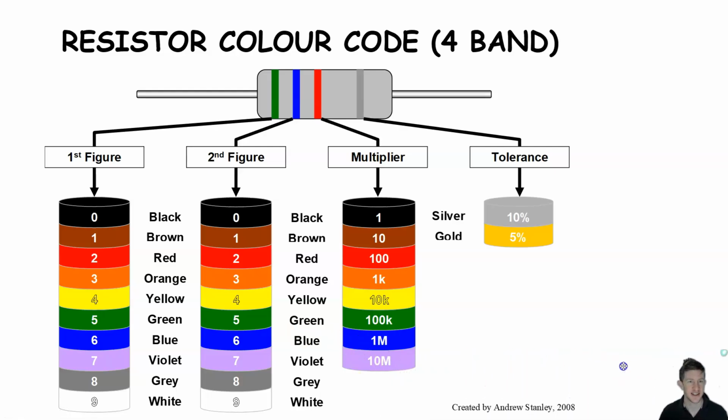This is a resistor color code chart. So a standard resistor in an electrical circuit looks a bit like this. It's like a little ceramic tube with metal ends on it, which are your wires for connecting, and they have all these colored bands. We'll use these a lot during the lesson and in future experiments when we build some circuits. This is a really good guide to help you figure out the size of the resistor. The first band gives you the first digit of the number, the second band gives you the second digit, and you can have more bands.